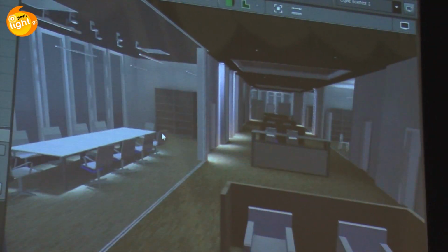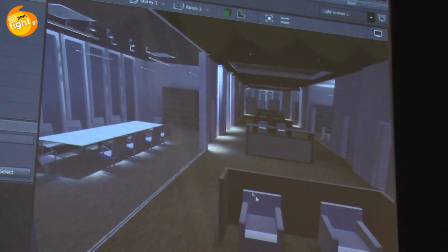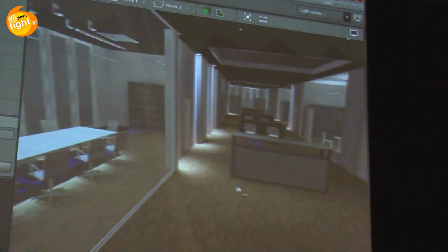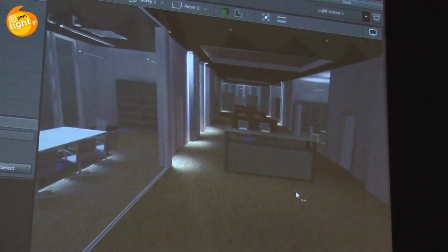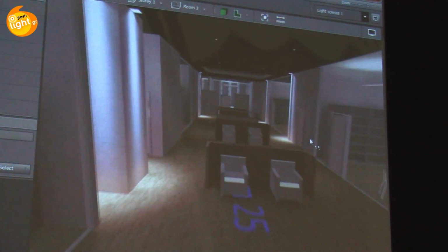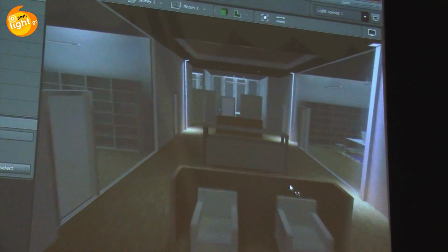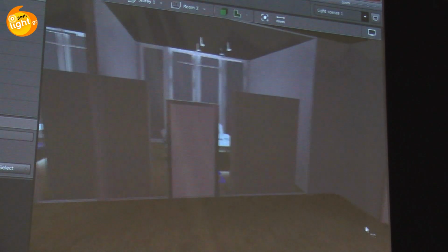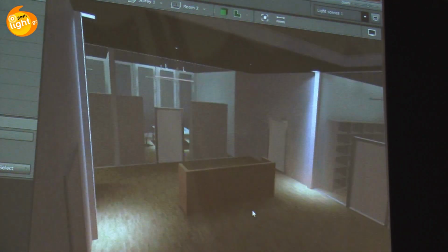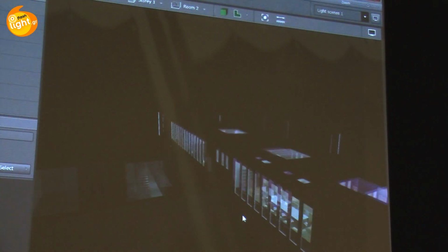We have real transparent glass. That was not possible in Dialux version 4. We have this transparency effect also after we did the Dialux calculation. You can move the observer through these complete building situation here, and then we can do the scale like this.